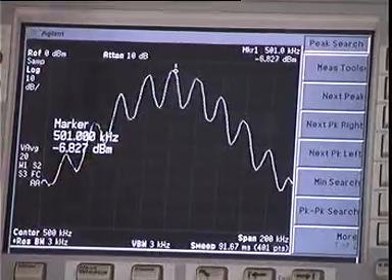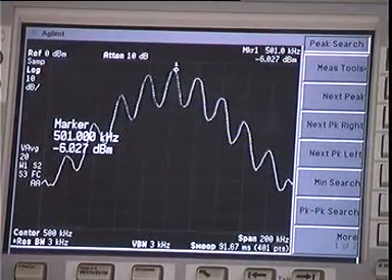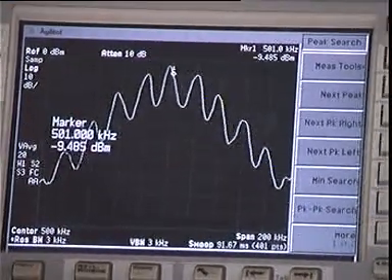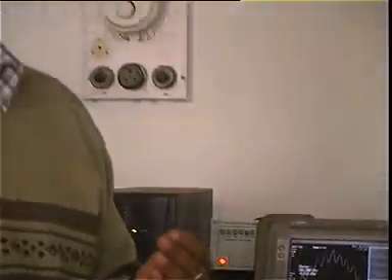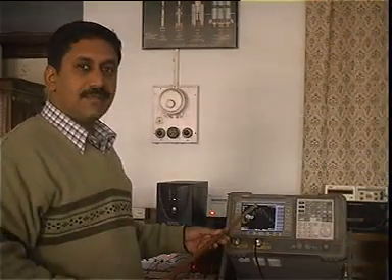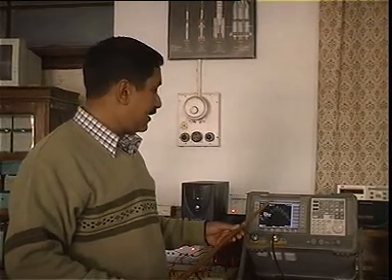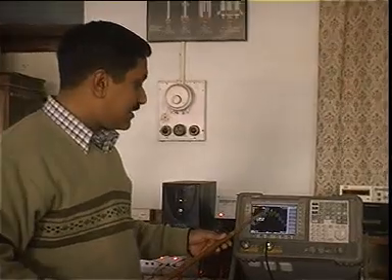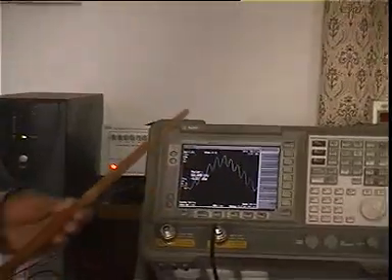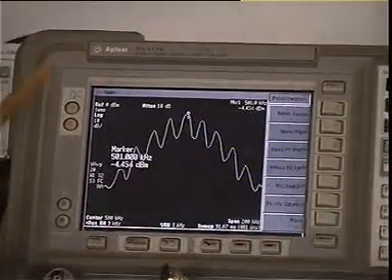It is possible for me to find out the modulation index beta if I look at the carrier. Remember that this beta is related to the peak message signal amplitude. Now, if I change the amplitude of the message signal, if I increase it, this beta value will change. Now this is J0 beta, if you look at the Bessel function representation of FM signals. As I change the beta value, the carrier power will begin to drop, and the number of sidebands would increase.